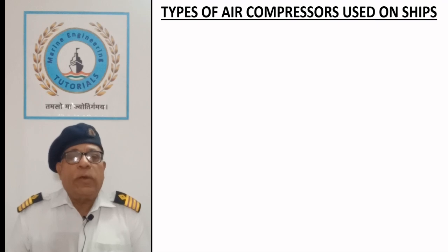Types of air compressors used on ships. Compressors can be broadly classified in two categories, mainly positive displacement compressor and rotodynamic compressor.